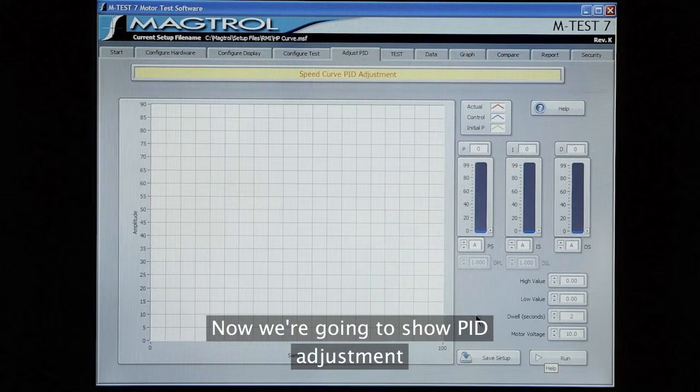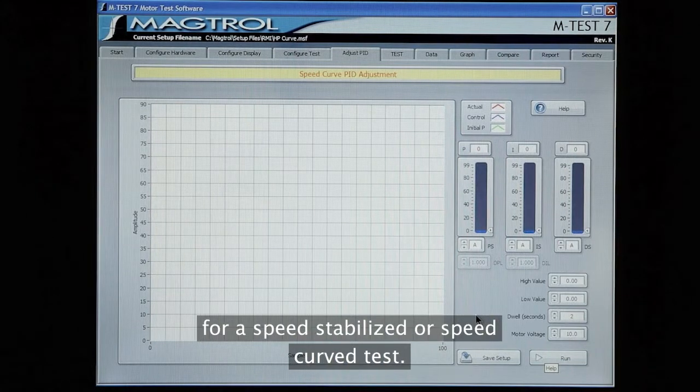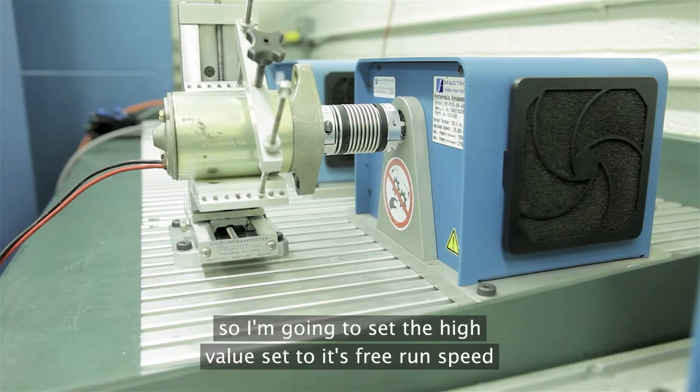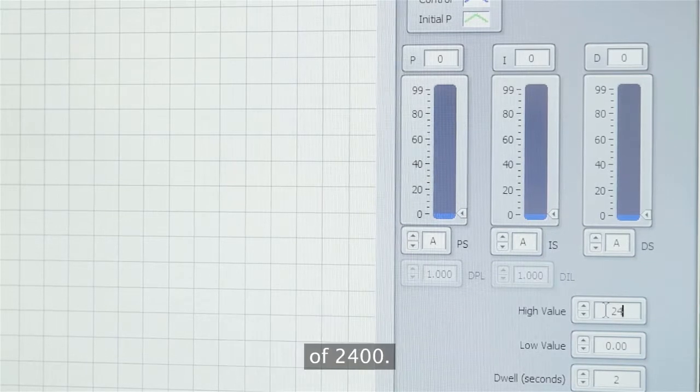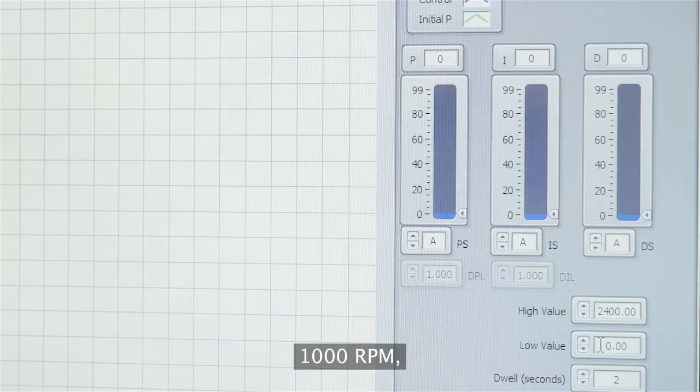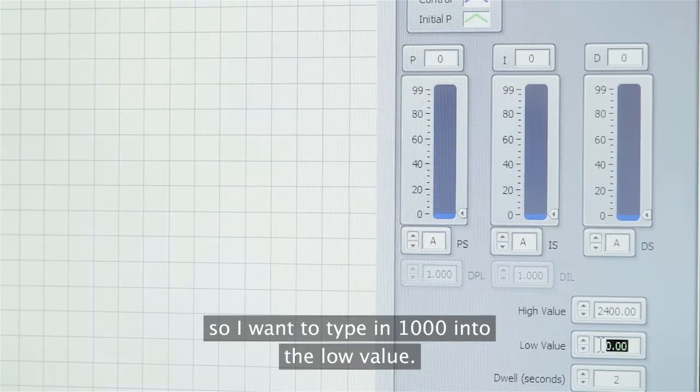Now we're going to show the PID adjustment for a speed stabilized or speed curve test. The motor we're using free runs about 2400 RPM, so I'm going to put the high value set to its free run speed of 2400. During the test, the lowest speed that we're going to run the motor to is 1000 RPM. So I want to type in 1000 RPM into the low value.